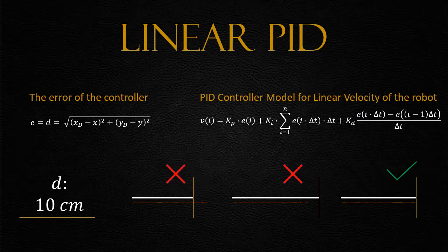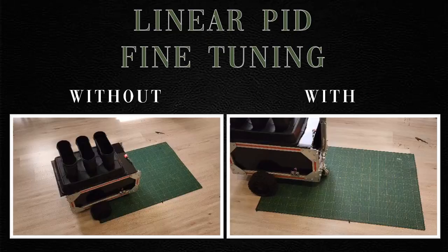In our kinematic control approach, the robot doesn't account for residual momentum when using constant linear velocities and energy cutoff braking. To address this, we implemented an additional PID controller to govern the linear velocity of the robot. This linear controller continuously assesses the difference between the current position of the robot and the desired coordinates. As the robot approaches the target location, the linear controller gradually reduces the linear velocity. This gradual deceleration mitigates residual momentum, leading to improved accuracy and overall precision in the robot's movement.